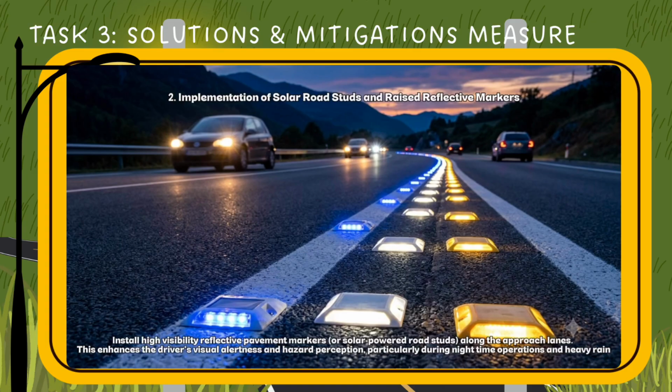Second, to solve the visibility limitations, we recommend the implementation of solar road studs and raised reflective markers along the approach lanes. This significantly enhances the driver's visual alertness and hazard perception, particularly during nighttime operations and heavy rain when vertical curves become hardest to navigate safely.